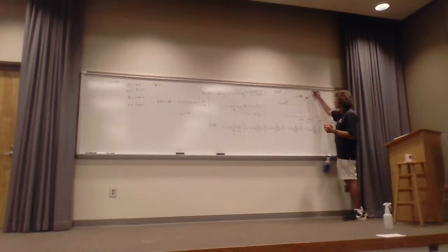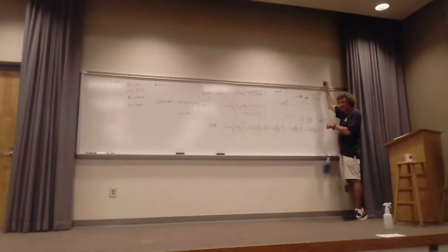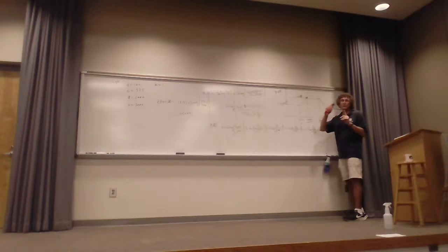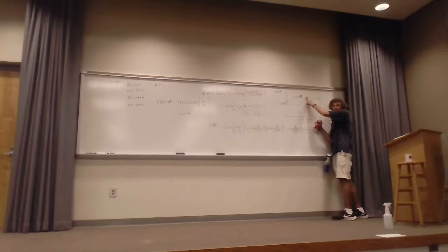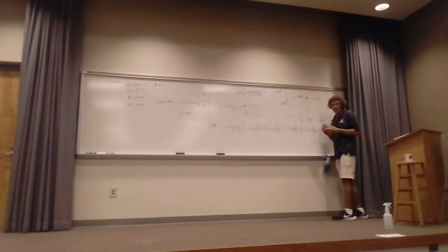Now, if it started going up at 40 dB per decade, then at this point I'd have to find what the value is here, and then I'd add to it plus 40 times the log of the frequency it finished at, divided by the frequency it started. So it's not the cumulative. Well, it is, but you don't add two 20 dB lines. If you know this value here and it starts going up from that point at 40, you know the slope of the line. You just say it's this value plus 40 times the log of the difference in frequencies. That's the key to remember. Make sense?